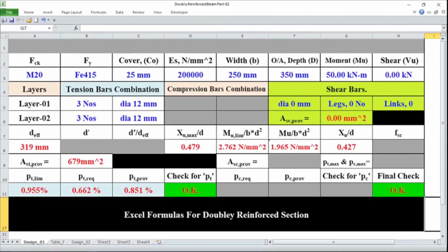Now, I'm displaying a dummy Excel sheet on this PowerPoint presentation to illustrate exactly what we're going to cover in this episode. In this sheet, you're looking at some adjustments for a doubly reinforced section, such as the introduction of compression bar diameter, number, and layers, as well as the area of compression steel, ASC. In all the bluish-gray cells, we're going to calculate the following in Excel.